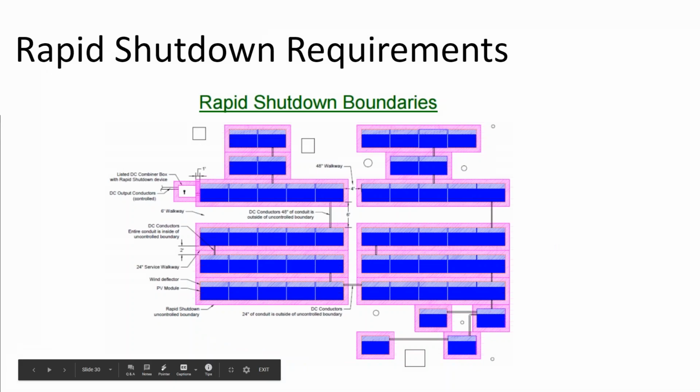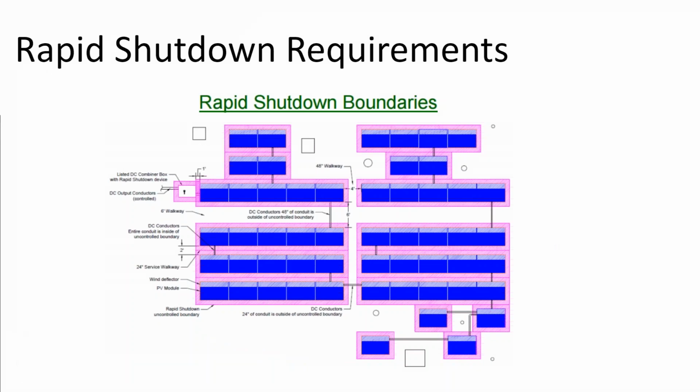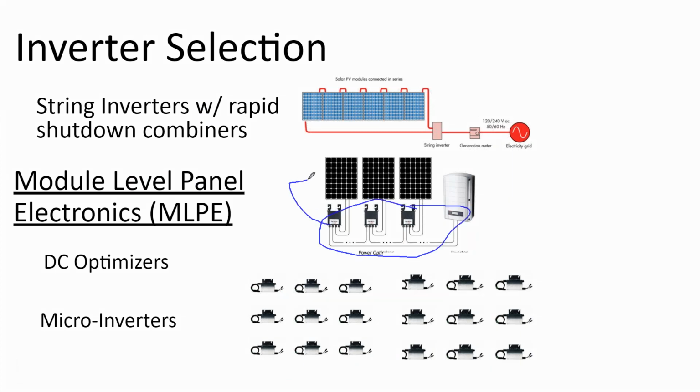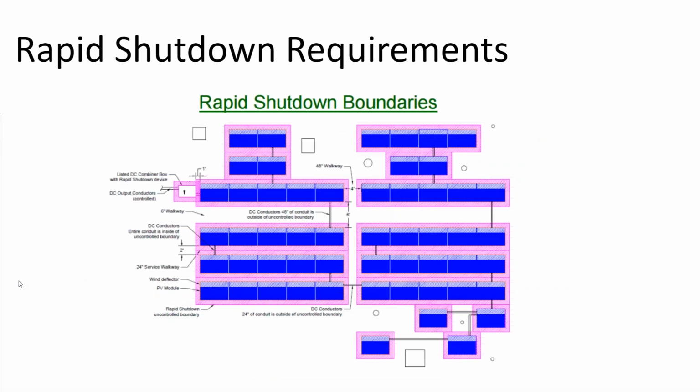And National Electric Code has effectively said, yes, we want you to use microinverters or a DC optimizer system, which still has the control boxes behind every single panel on the rooftop. National Electric Code has pretty much said you have to put these controllers behind every single panel on the rooftop, because of fire safety. Basically what code says is you have to have a way of turning the solar array off, but there's no off switch to the sun.